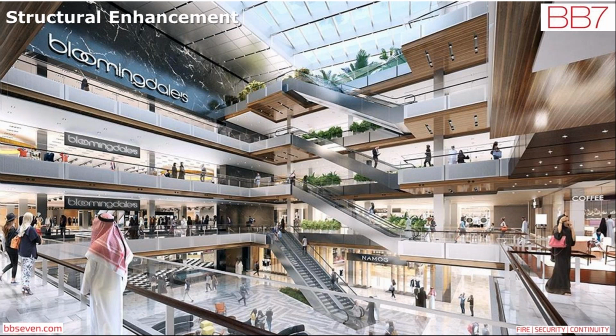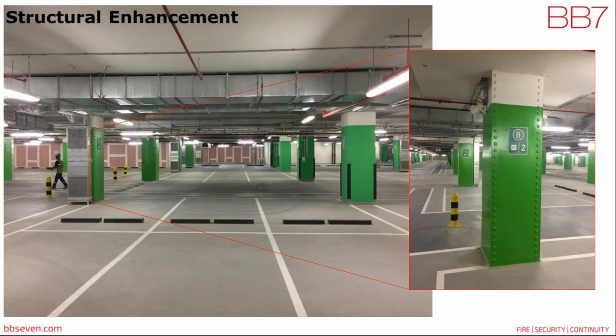The cantilever design was particularly vulnerable to any additional loading with blast, and as a result, enhancement was required. And this was the answer to harden the structure to prevent progressive collapse. The solution was for most of the columns to be increased in size, and some, due to the atrium design, required additional steel jackets. But firstly, the measures are hidden. Most visitors wouldn't even know the purpose of the steel jackets. And secondly, the cost was much lower than originally envisaged.